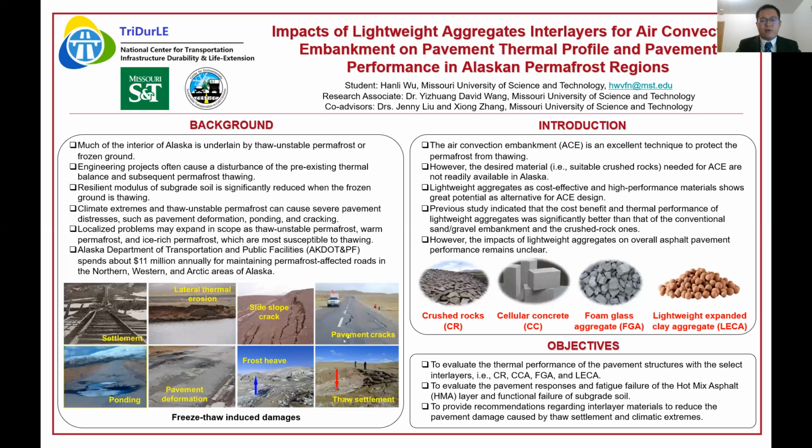Previous studies have confirmed that ACE can be successfully used to protect roadway embankments in permafrost regions. Our recent study indicated that the cost benefit and cooling performance of the cellular concrete ACE was much better than the crushed rock ACE and the conventional salty sand gravel embankment. However, the impacts of lightweight aggregate on overall performance of pavement structure remain unclear.